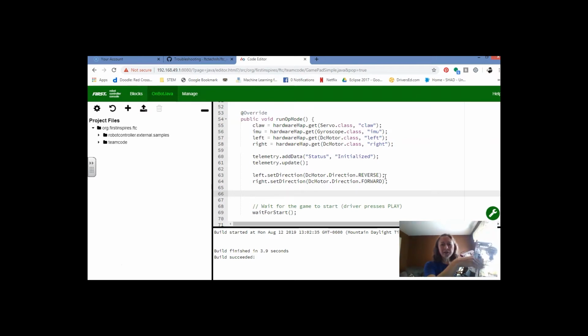These servos go 180 degrees, and the way this is mapped in the software is that pegged all the way one way is 0, and then pegged all the way the other way is 1. So at 90 degrees, that's 0.5 because it's halfway between 0 and 1. I don't know for sure at first whether my servo is going to be starting at 0 or 1.